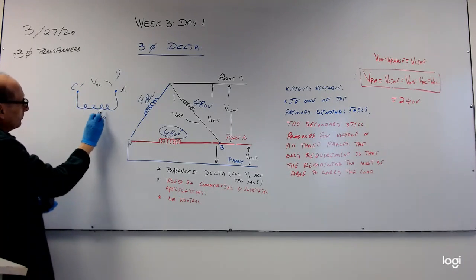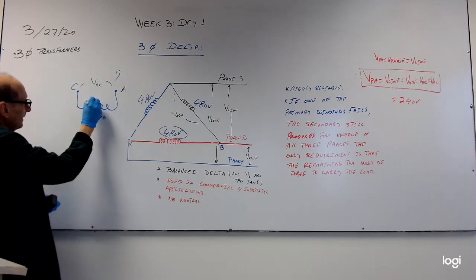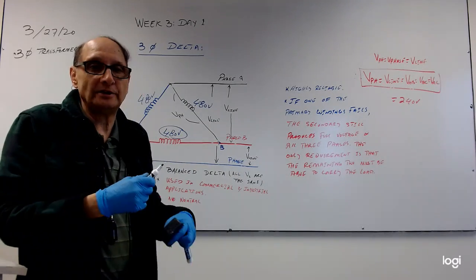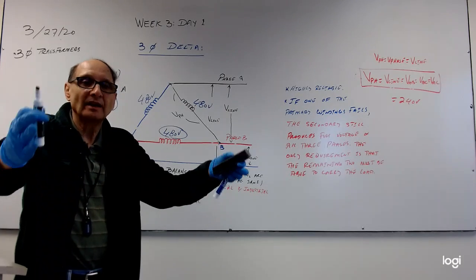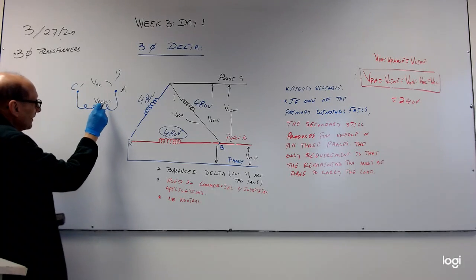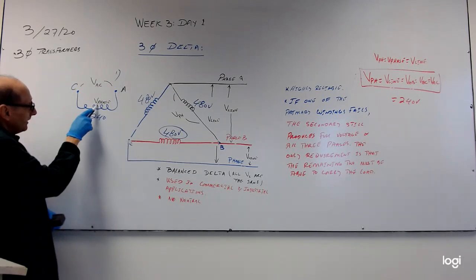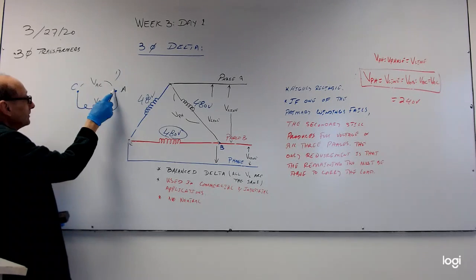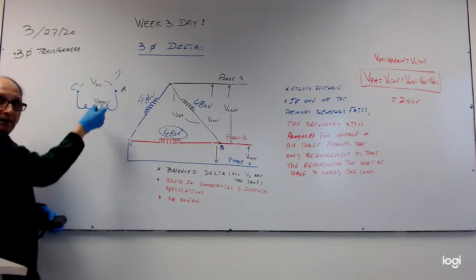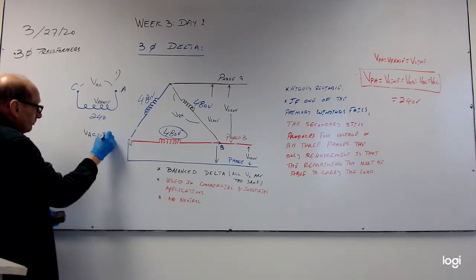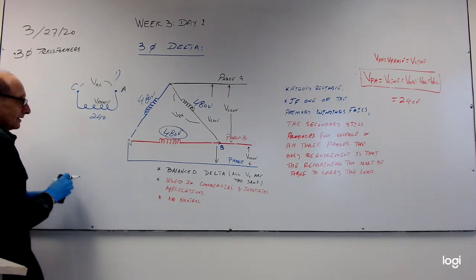If this is 240 volts, let's call it V phase. V phase is the same as winding voltage, the voltage across a single winding. So this is one of the transformers here. This is one of the windings. That's called phase voltage, 240. How much is between these 2 points? Phase is right across from that terminal. VAC, 240. Okay. Same thing happens over here.